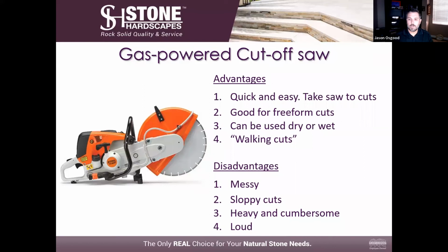And what I mean by walking cuts is if you have long cuts to make and you install your pavers outside the finished edge of the deck, chalk line where your cut needs to be, and a gas-powered cutoff saw is very good about just plunging the saw itself into the stone and walking that cut. So you can walk that entire cut regardless of how long it is.